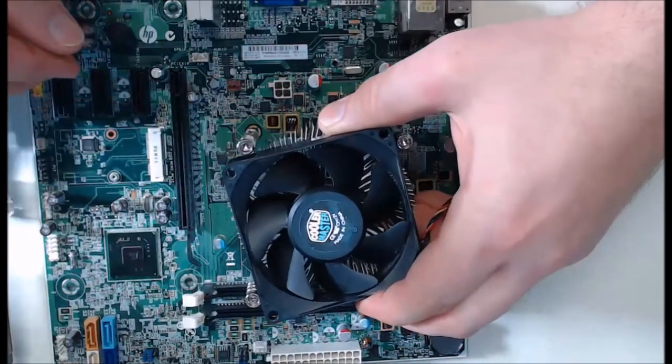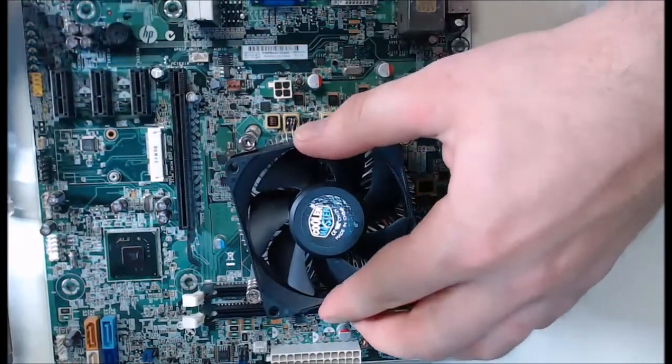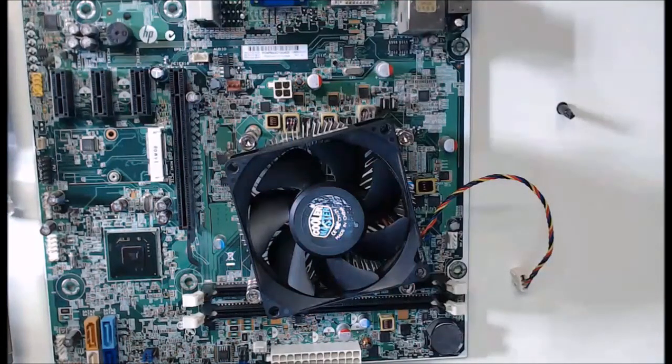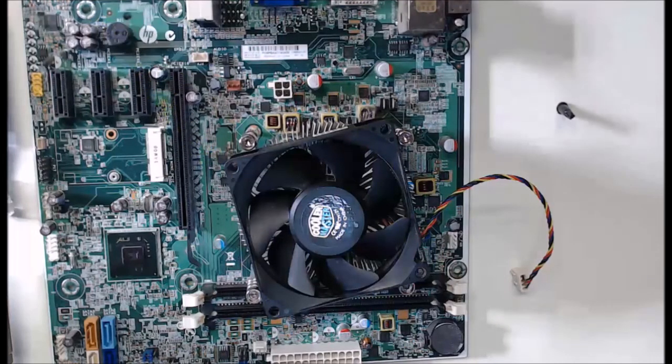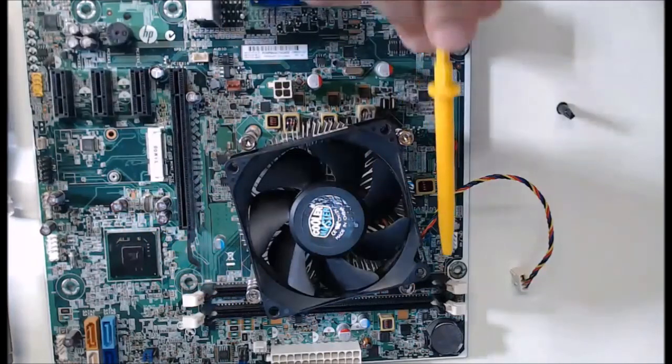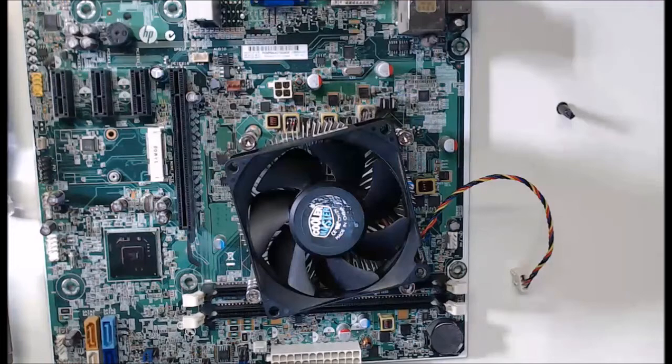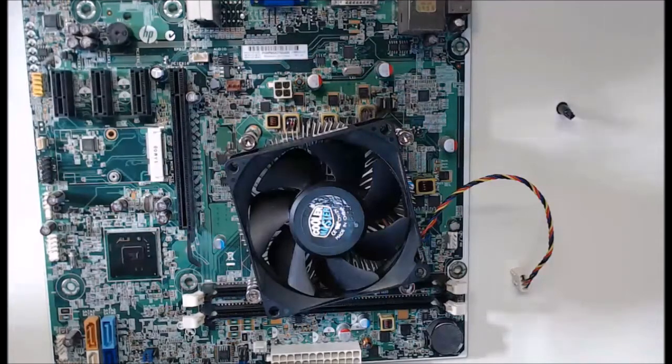After positioning the heatsink correctly so that it aligns with the heatsink screws on the motherboard, we will screw in the 4 screws in a specific order. It is best to screw one corner first and then go to the opposite corner diagonally from it. This will help ensure we have a flush connection between the CPU and thermal paste and the heatsink.